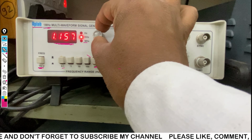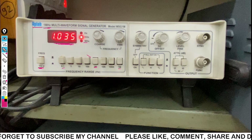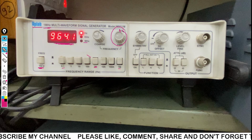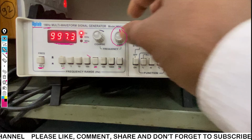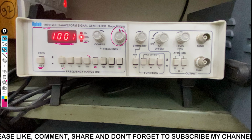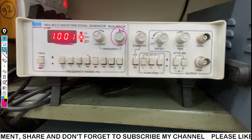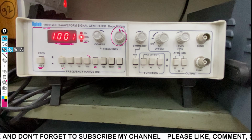Whenever we are adjusting the frequency, we should keep the fine button at the center position, and then we can do the adjustment using the coarse button. If I want to adjust to 1 kilohertz frequency, I put fine at the center, then using coarse I will go to the nearest value, and then using the fine button I can select the particular frequency.